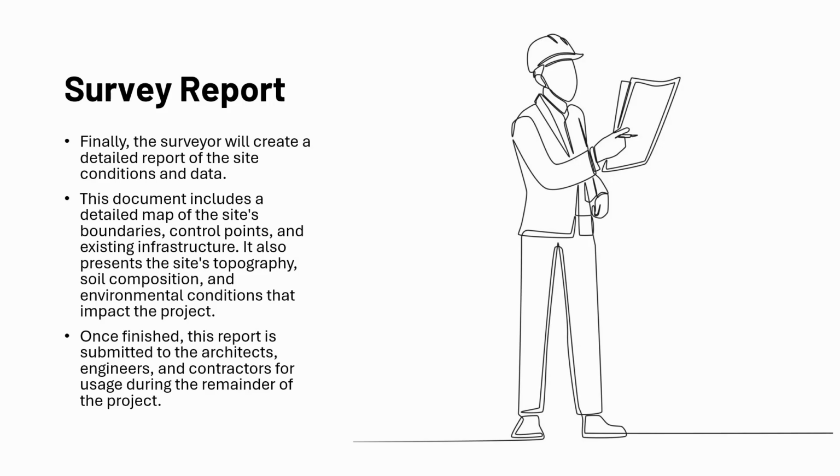So throughout that project, people are going to be referencing your work. When I talked about the intermediate control networks during the boundary and control phase, establishing those for potential alignments or for roadway projects, those points that you set, that horizontal and vertical control that you set, is going to be used, and vitally used, throughout the project for where new construction gets put.